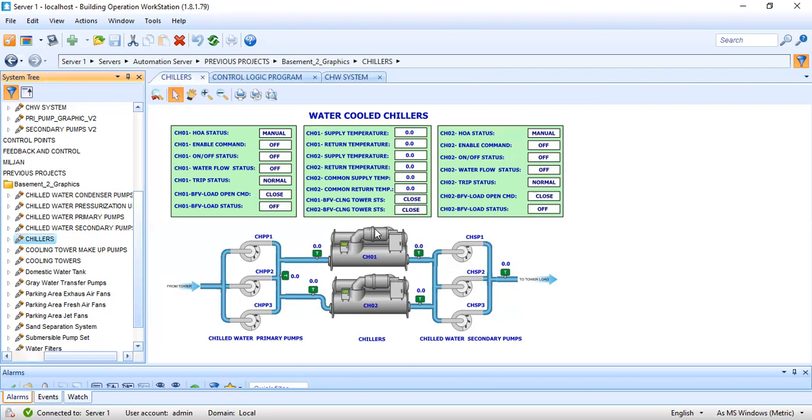So in a water cooled chiller, likewise we have primary pumps. Then we have also a secondary pump. Now the primary pump's purpose is to cool... actually this should not be from the tower. It should be from the cooling load or from the building. It should be from the building, not from the tower. So I need to change this to the building.